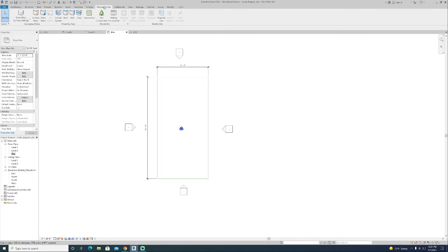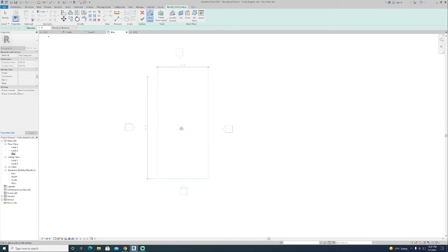So we'll go up to our massing and site tools and click on that topo surface button. I'm going to put some points in at 0 feet 0 inches. I'm going to start in the top left-hand corner, picking right at the intersection of that upper leftmost boundary. Then we'll go to the upper rightmost boundary. I'm going to put a couple of points in around the middle of the property, so we'll find the midpoint along the line. The midpoint is going to be that purple triangular inference.